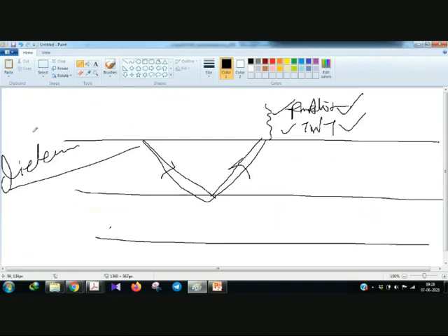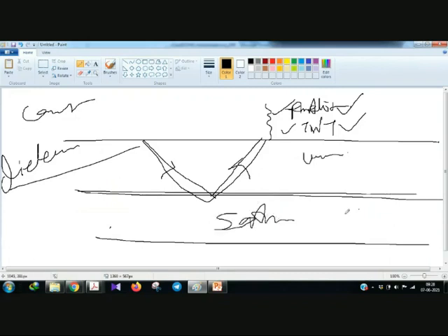One more thing they basically depend on is the dielectric contrast. Suppose this is a water table. This portion is your saturated condition, and this is the unsaturated condition. Water has a very high impact on the GPR signals, because water has an epsilon r, or kappa, of around 81.